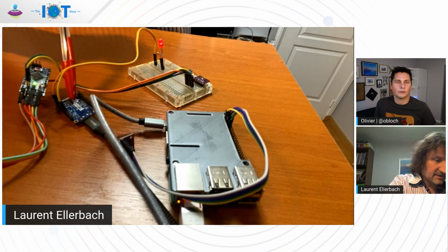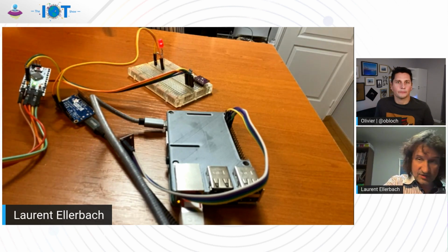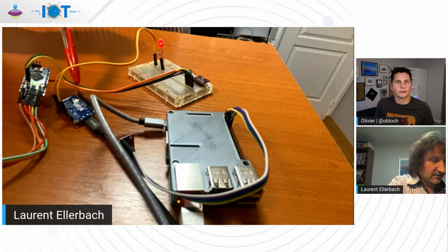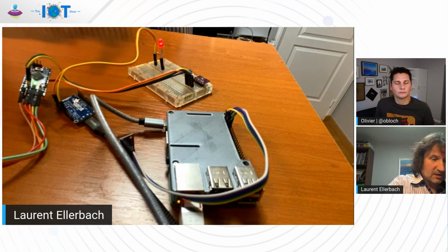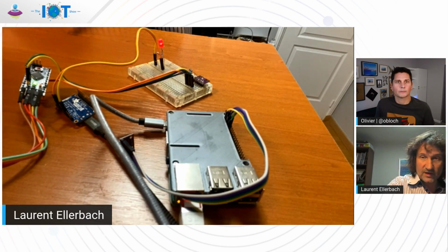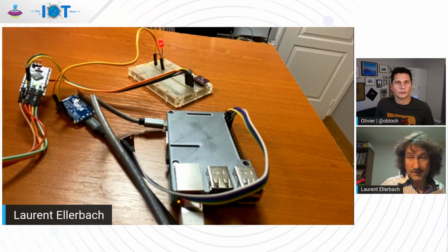The first one, for example, is this extender. It's an FT232H. There is as well another one that you have in the repo, FT4222. I can do a quick demo as well for this one. And we have here a simple Arduino plugged with a serial port to my device. And that will bring the missing GPIOs, SPI, and I2C support that you have on Windows.